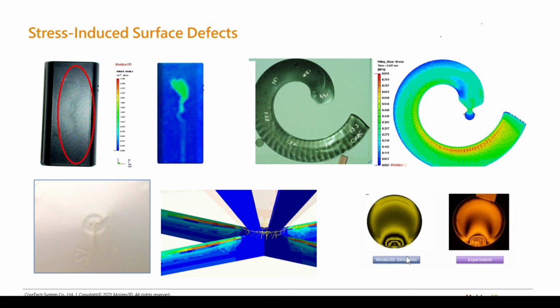And then over here we get an optical stress plot. This is what we call a fringed pattern. Wherever you go from a yellow color to a black color, or orange and black over here, that's where there's a gradient of stress. Gradient of stress, as far as optics are concerned, impacts the visual quality of something like a lens. If you were to look through a lens, you'll sometimes see these visual defects. So you can see that right at the gate, which is at the bottom here, that's where you're getting a high amount of stress gradient.